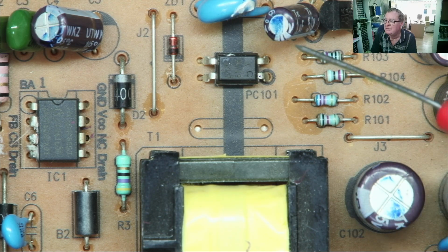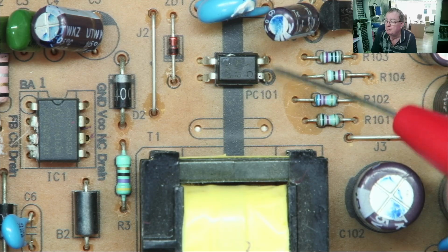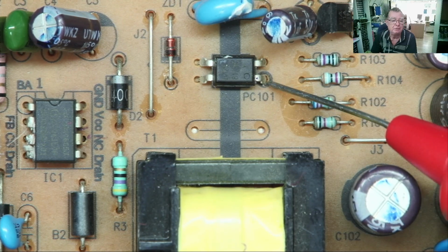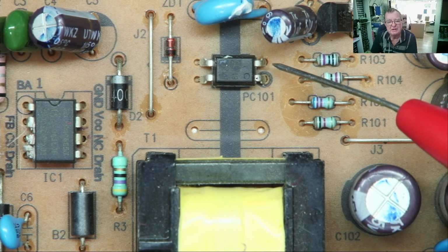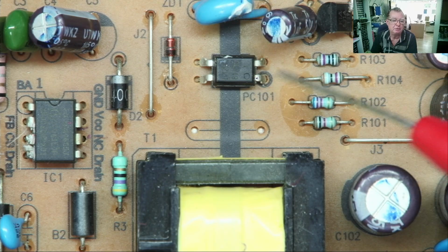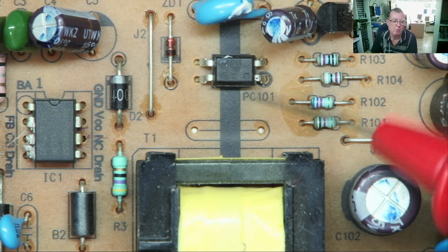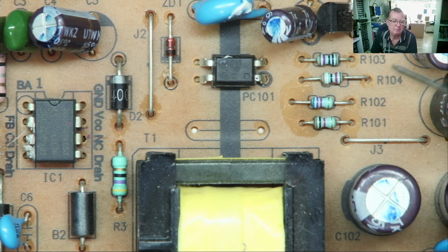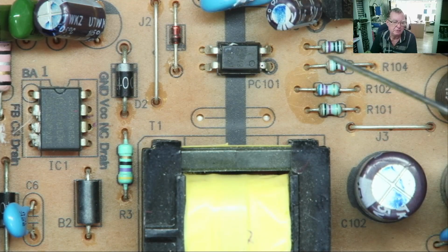The way to test this is in circuit. Use a multimeter or something similar to apply a voltage in diode mode across here. Light the LED up. If the LED is intact, you should see 1.05 plus or minus a very small amount, but between 1 and 1.1 volts across it. That's the voltage drop of an infrared LED. Okay? If it's anything less than 1, you've got a problem somewhere, probably in the surrounding circuit, and if it's more than 1, you've probably got an open circuit LED.